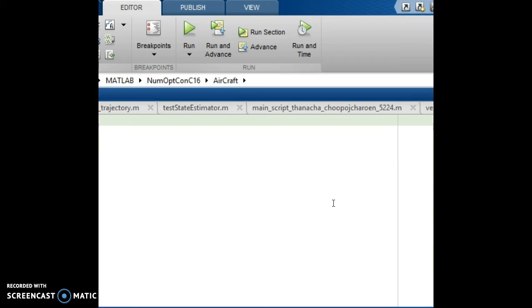We're basically given a path in 2D space, and a sequence of yaw angles that correspond to that path, and we want the robot to stick with the path. It can deviate a bit, but generally follow the path. At the moment I didn't write the trajectory generation code, so I just give it a random trajectory to follow. It's a smooth one, with acceleration that is not that large, so we can ensure the robot can follow relatively well. Okay, it's going to run a while, so I'm going to describe the dynamics of the system.